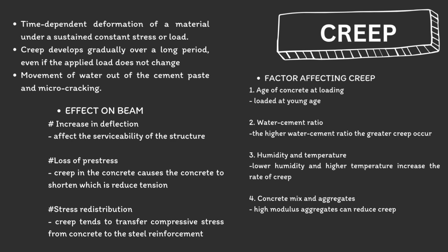Next, we move to the factors affecting creep in concrete. At first, the age of concrete at loading, meaning that the concrete was loaded at a very young age. Next, the water-cement ratio. It shows that the higher the water-cement ratio, the greater the creep that will occur in the concrete.